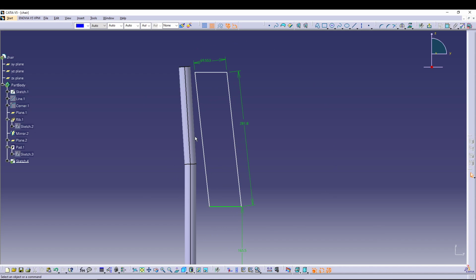The next thing that we will do is we'll project this edge. So for that, let's go for project 3D silhouette edges. Select this one. Okay. Now you can select this and delete this. We don't want that. And select this, make it construction, and then select this point and this point.